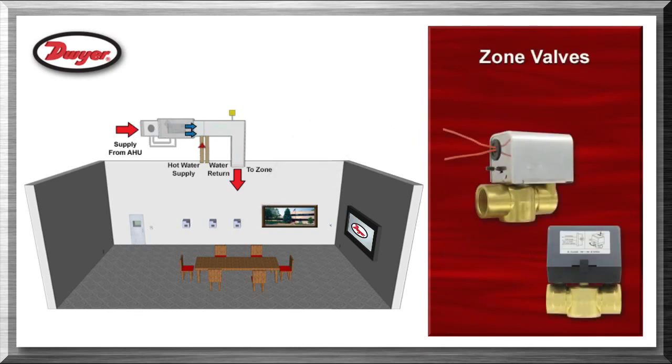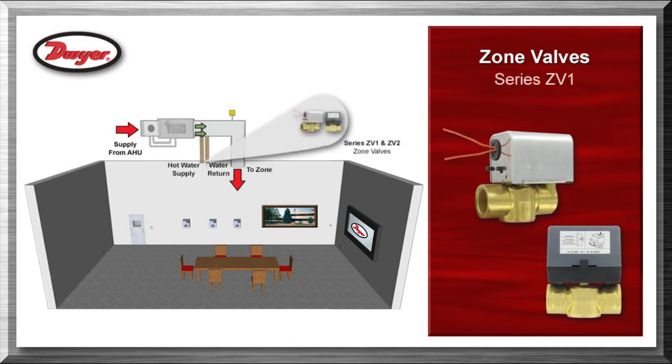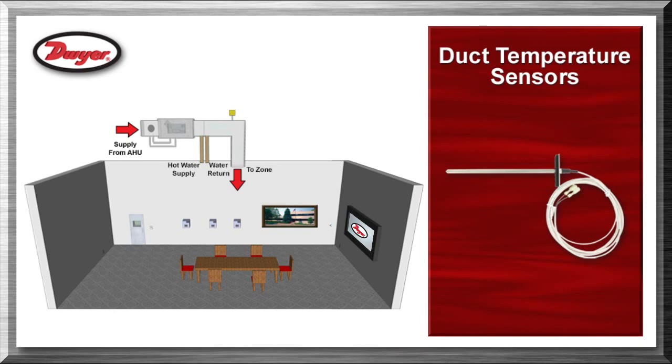VAV systems can include reheat coils of hot water that the air flows past to heat the air. Zone valves, series ZV1 or ZV2, are used to change the amount of hot water added to the heating coil, thereby changing the air temperature. Duct temperature sensors, series TED, monitor the air supply duct temperature coming into the VAV terminal and also monitor the air discharge temperature being supplied to the space.